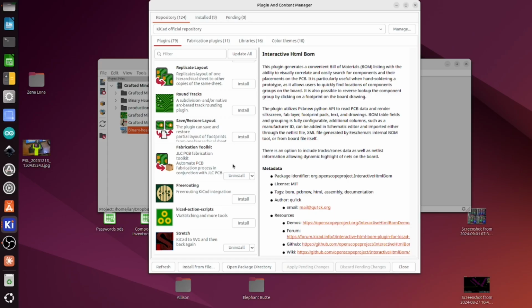I've seen in Facebook groups in the past people using KiCAD with a board that has an oval-shaped footprint, or an oval-shaped hole in a footprint, and they send it off to JLC PCB and they get back a little tiny round hole where they were expecting a big oval-shaped hole, and they're wondering what happened. So I'm wondering if maybe this addresses that problem.